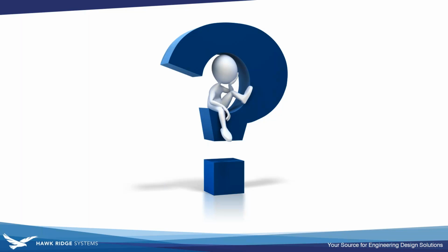A real question that did come in: is there a viewer for out of the house? Unfortunately, no, because everything is a database-driven application. Pretty much the majority of the work is databases. So we found most people are okay with printing to PDF or exporting to DWG, and most people can do that. Or you can even export to eDrawings, which is also a free viewer for all SOLIDWORKS files. So there's availability out there for people to view it without being connected to the database.